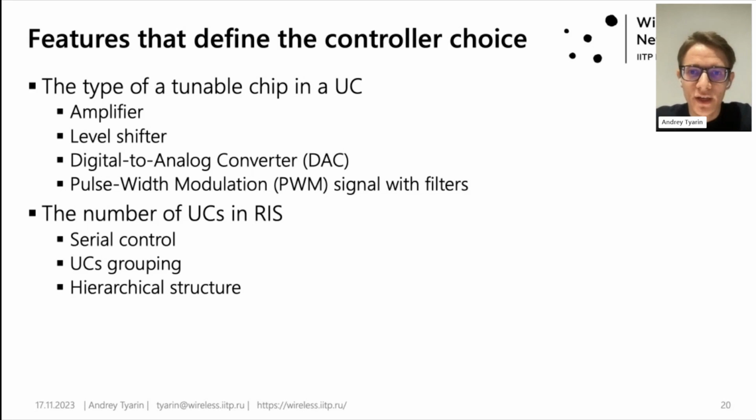If the controller lacks analog outputs, digital to analog converters realize conversion from a digital signal into an analog one at the output pins. Another way to get an analog voltage using digital outputs is to use a PWM signal with a low pass filter. The PWM signal is converted into an analog one, for example, via an RC low pass filter.